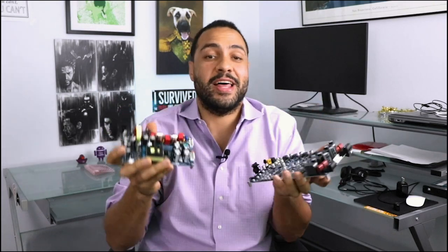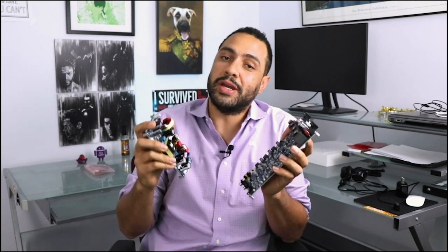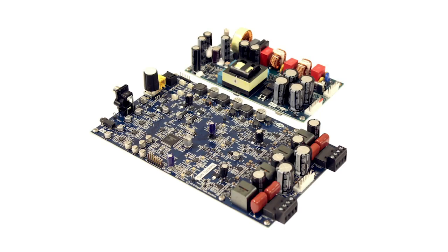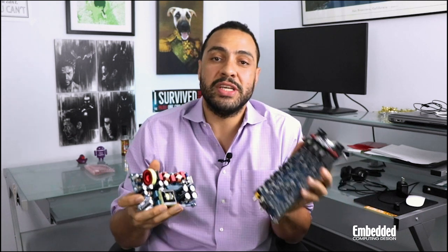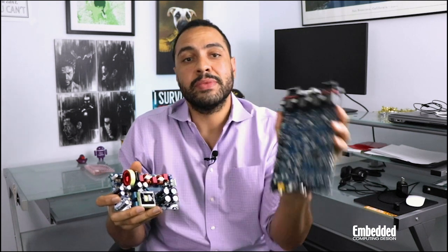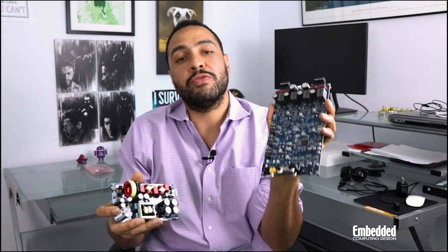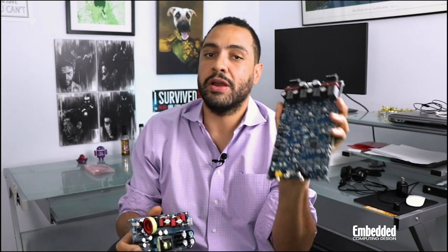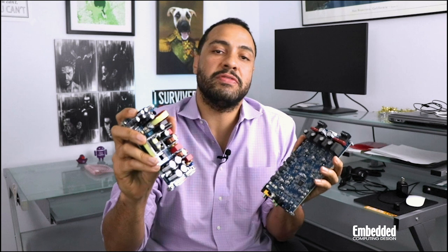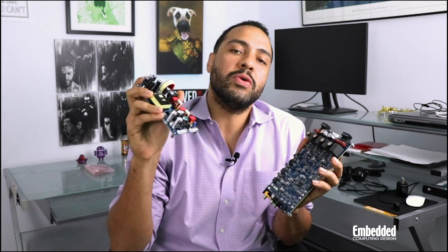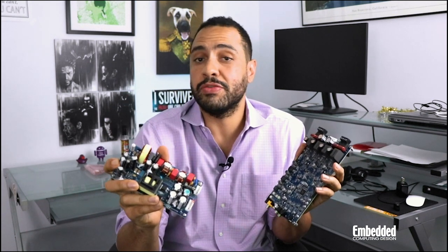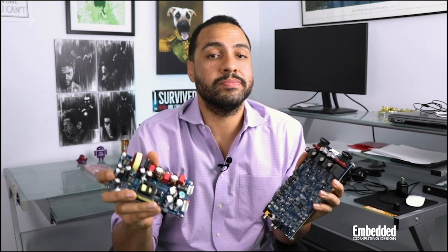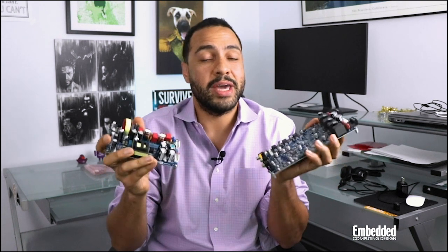Holy DevKit, this is a lot of equipment. And that's because the GS EVB AUD Bundle 1-GS is, well, a bundle of two GaN Systems evaluation boards. One of the boards is the GS EVB Audio Amp 1-GS, which sports a 400 watt Class D audio amplifier, while the other features a 650 volt switch mode power supply with power factor correction that can be driven from a PFC or LLC controller. And being GaN Systems, both of these boards are powered by Gallium Nitride technology.